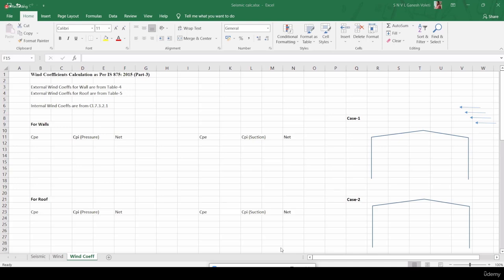Yes. Any other thing? If a building is in a confined space with larger buildings in all directions, is wind direction applied or not? I told you there is terrain category 4. You have to apply terrain category 4. You have to apply wind pressure on the steel structure for sure. There is no concept of not applying any wind pressure on the steel structure. You have to apply wind pressure for sure, but you have to take terrain category 4 in that case.